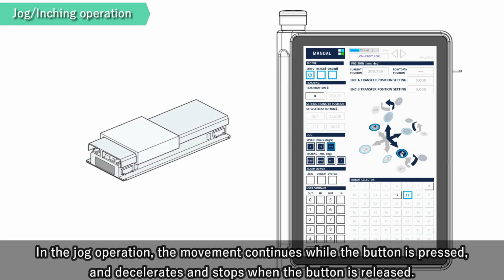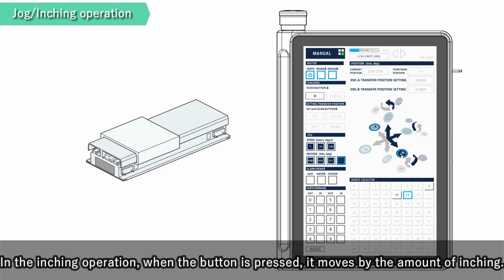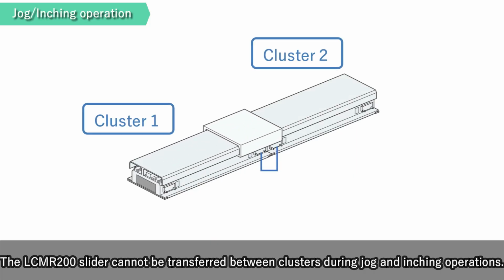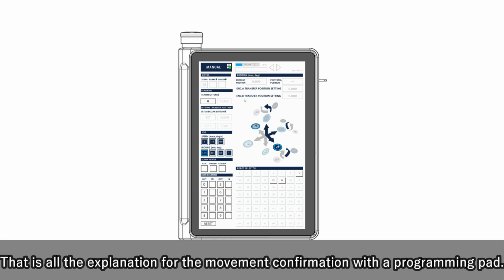In the jog operation, the movement continues while the button is pressed and decelerates and stops when the button is released. In the inching operation, when the button is pressed, it moves by the amount of inching. The LCMR200 slider cannot be transferred between clusters during jog and inching operations. That is all the explanation for the movement confirmation with a programming pad.